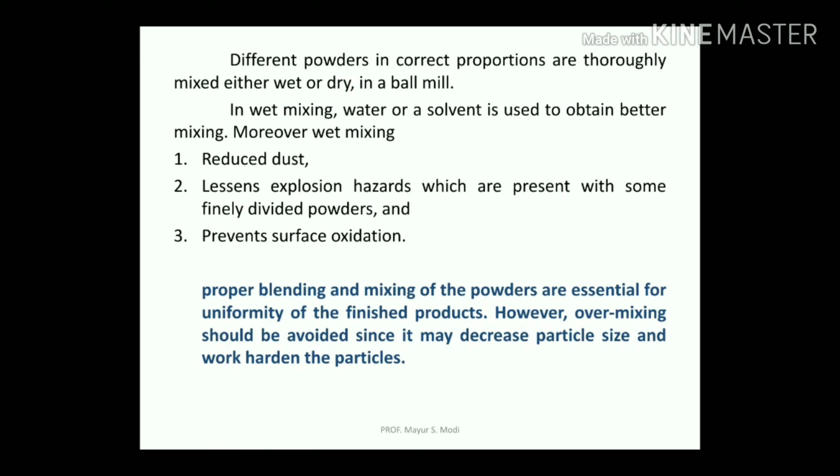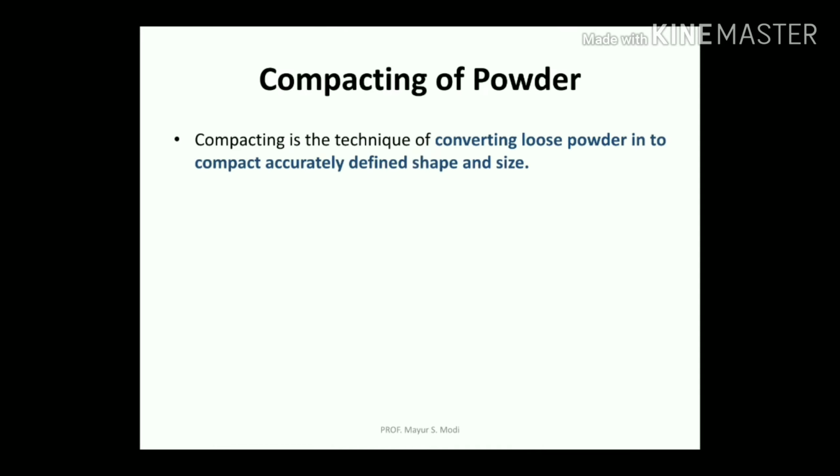However, over mixing should be avoided since it may decrease particle size and work harden the particles. Compacting of the powder, or you can say the sizing and shaping of the powders. Compacting is a technique of converting loose powder into compacts of accurately defined shapes and sizes.